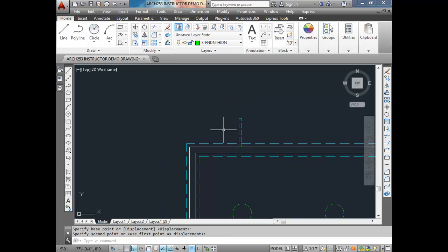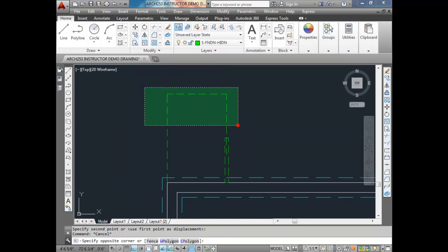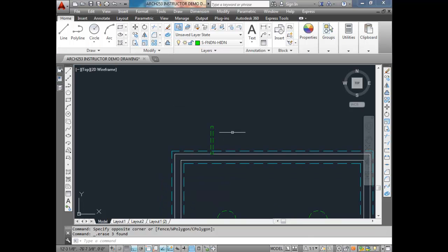I'm actually going to move that and attach it to the wall, and I'll locate it along the wall in a second. I'm going to use a construction line to locate it. I'll come up, I'll come over, and I notice the dimension there on the plan is 4 feet. That should be the midpoint of that particular precast bracket. So now I'm going to move this so that it's connected to the midpoint. And then I'll delete my construction lines.